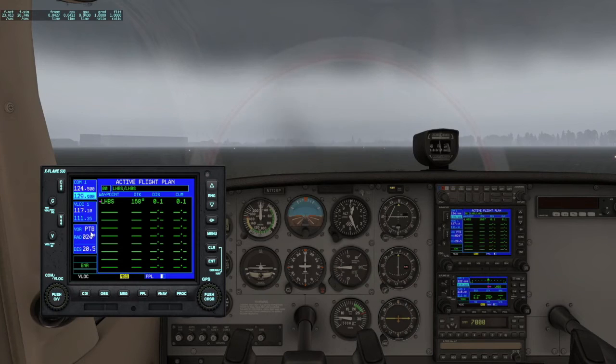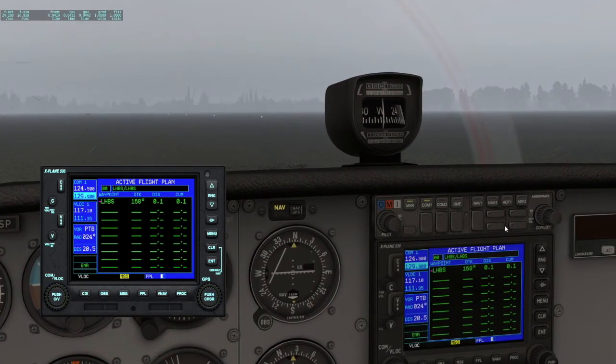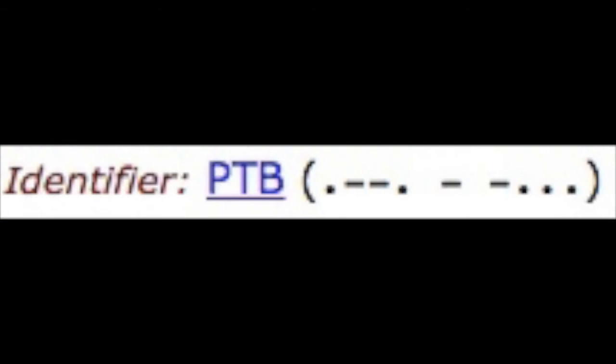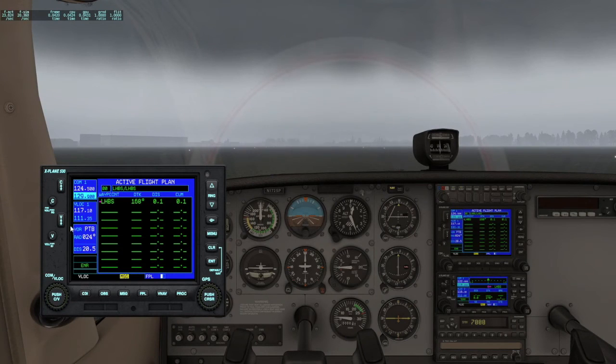And once you tune in the frequency for the VOR, the first thing you have to do is to identify the VOR by listening to the Morse code, which is dots and dashes, for that particular VOR station. Once you can hear it clearly, that means it's operational and it's functional. We're going to turn that off, and then we come back again to our display here.